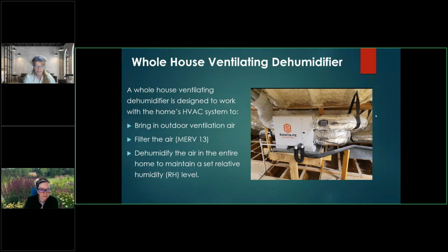As Ken would say, AC is king, dehumidification is queen. When the AC is sleeping, that's when the queen, the dehumidification, really shines, especially in those shoulder season and overnight times. A lot of times overnight, people get up and crank down a thermostat. It's not because it's a temperature thing. It's typically because it's a moisture thing.